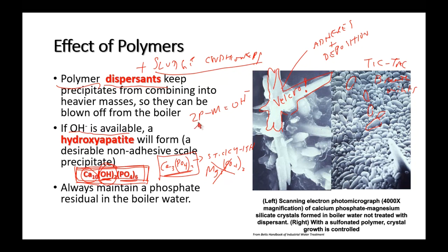We take a boiler water sample, we do the P alkalinity, and then we do the M alkalinity, and we do a little bit of math, and it tells us how much hydroxyl ion is in the boiler water, and maybe we have, say, 150 to 300 parts per million of hydroxyl alkalinity. Okay, maybe that's our control range. And why do we do that? To control pH, so we don't want any acid attack in the boiler.